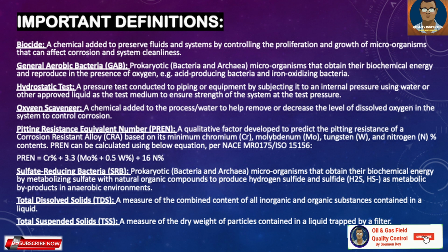Hydrostatic test, we know this: a pressure test conducted on piping, equipment or pipeline by subjecting it to internal pressure using water or another approved liquid as the test medium, to ensure the strength and integrity of the system, that there is no leak at the test pressure.